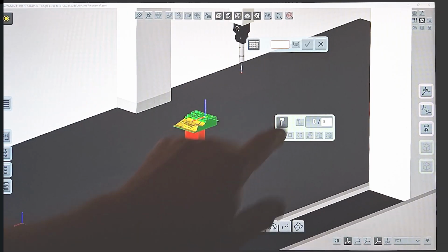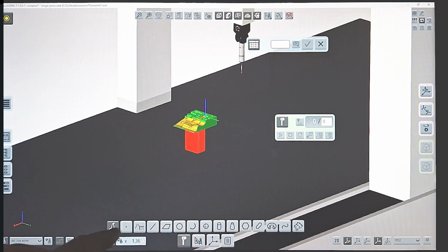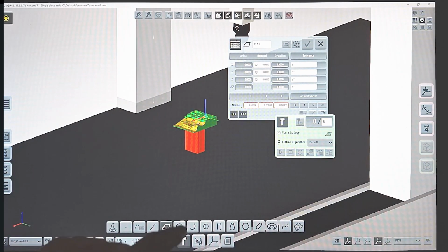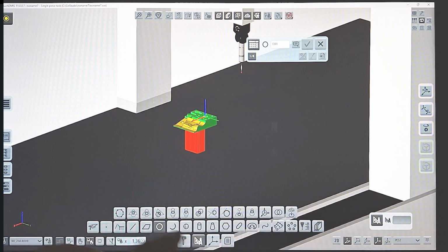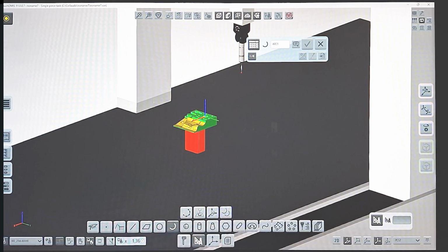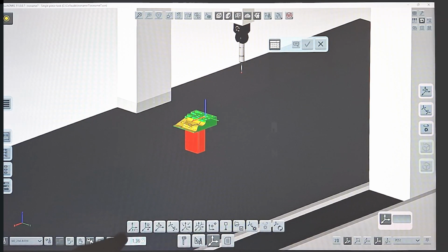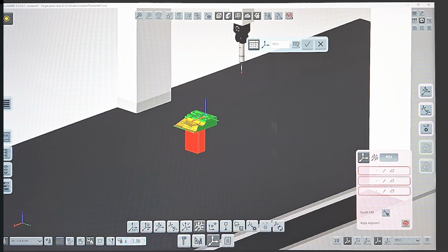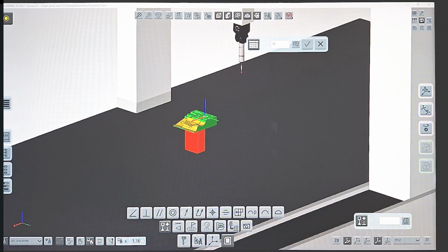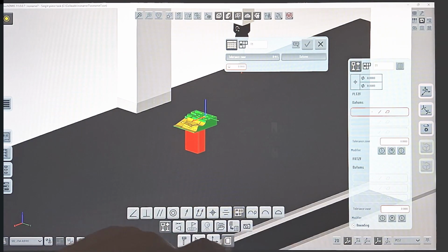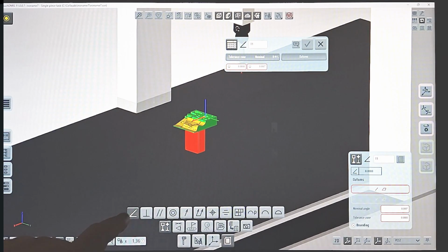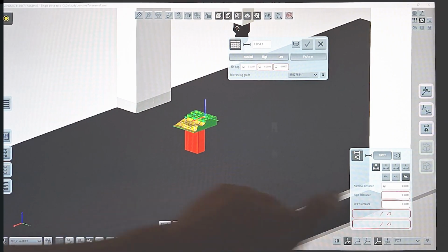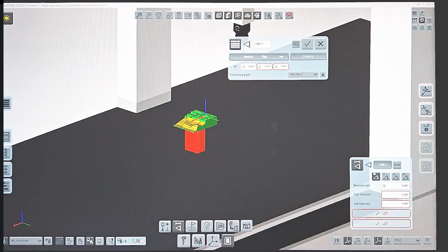At the bottom of the interface, we have the inspection elements: points, edges, lines, circles, and so on. We have all the construction for the elements. For every element, we have all the possible constructions that can be applied. We have all the alignments: 3-2-1 alignments, hole in 2 planes alignment, best fit alignment, RPS alignment. We have all the GD&T standards applied: true position, composite tolerance, profile, surface profile, angularity, perpendicularity, distances, angles. So, all the geometries can be applied within the software.